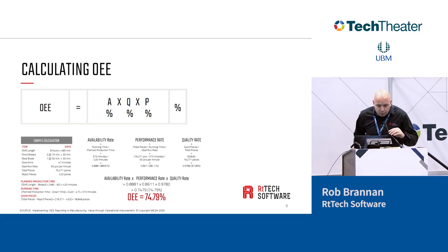And that's the great thing about OEE. Once you start drilling into it, it begins to highlight maybe problem running products. I've seen it a lot in processes where you've got a production line where you may run product A on line 1 and you're getting a really good run rate. You switch to product B, you're going to be getting a lesser run rate. Maybe the component you're putting down that line is bigger, it's heavier. Maybe the quality rate's being affected. These are all things to consider, and it's only really when you start capturing that information real time that these things start coming to life.